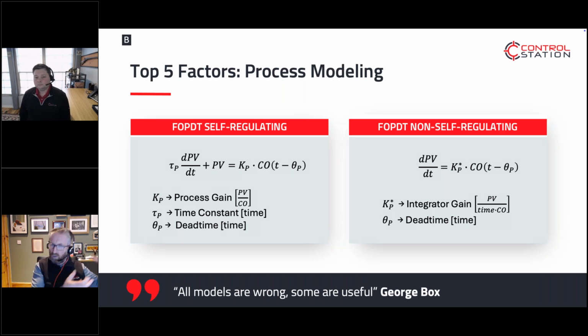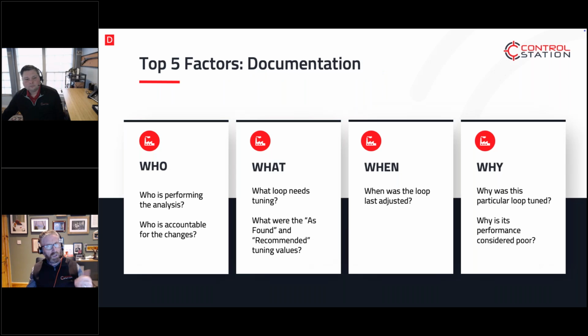With all of that information pulled in, we can then start to do tunings, and from the tunings, we're back to this document, the who, what, when, why, the "why am I here" question. How is it performing? What is it doing? What do we need it to change? Again, I always go to that "why am I here?" You've been pulled in front of this PID for some reason. Can you tune that loop, either for commissioning or through operations, because it's not doing what we wanted it to do? Analyzing that from trends, from operations discussions, pulling all that information and recording it.